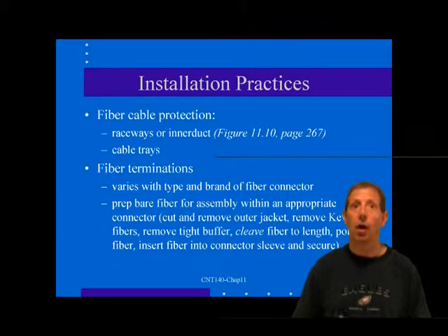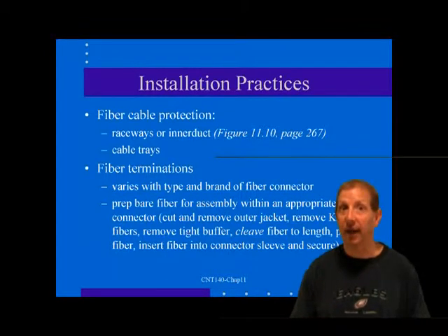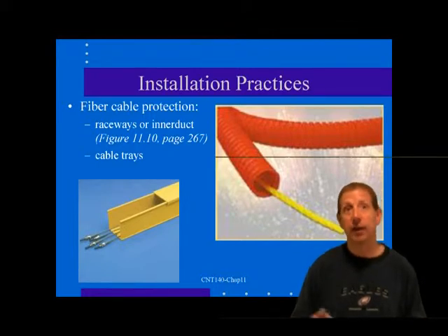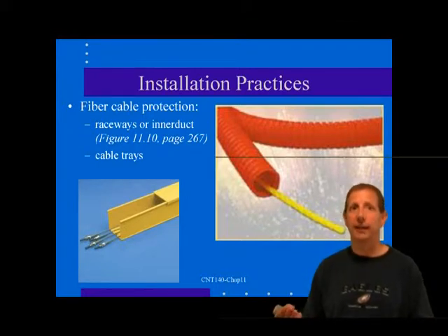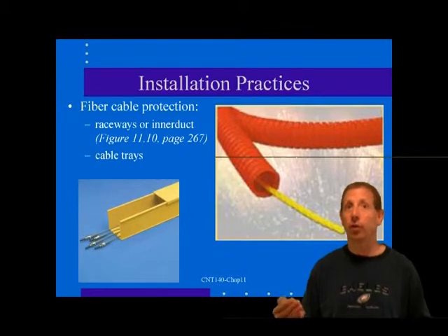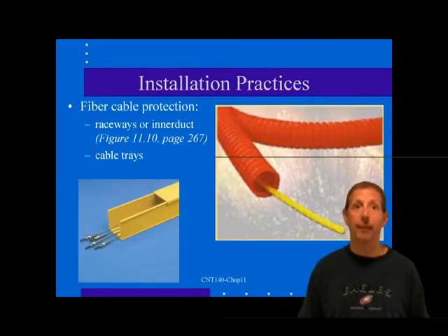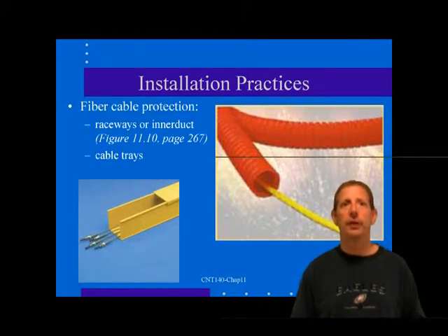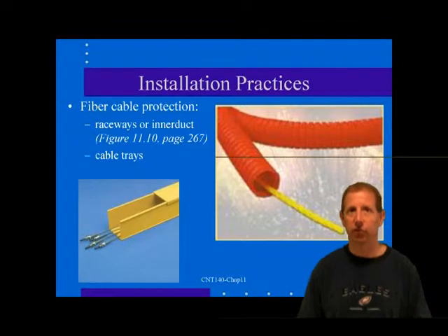These fiber runs will require the use of moderate jacketing, trays, and raceways to provide the appropriate amount of additional physical protection. Blown-in fiber places relatively unprotected strands inside plastic tubes that have been pre-installed between the TR and the work area. The tubes are technically raceways. They must meet all the flammability and smoke requirements of any plenum-rated device, if necessary. Likewise, the enclosed fibers must be appropriately rated for the installation location.